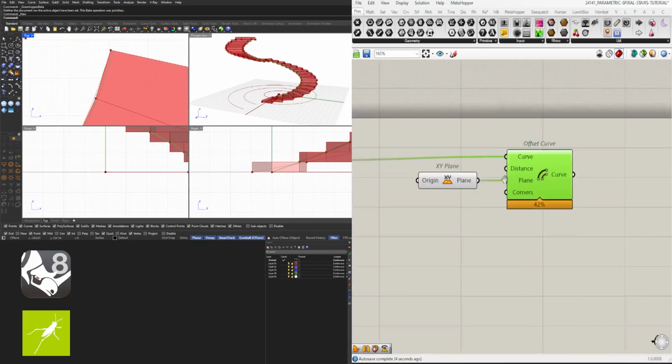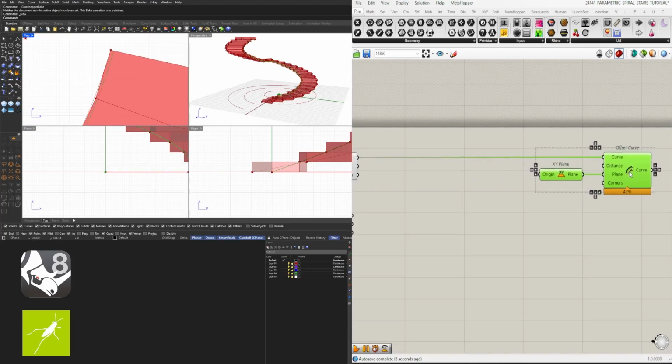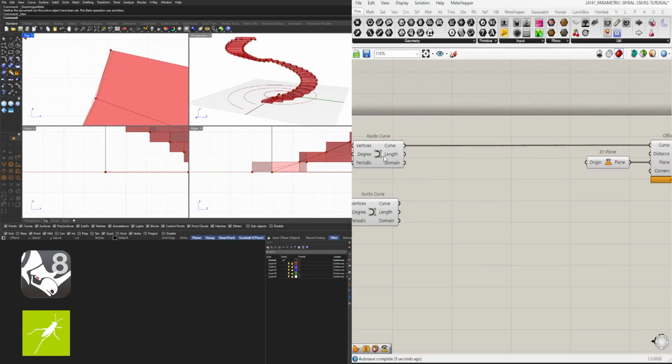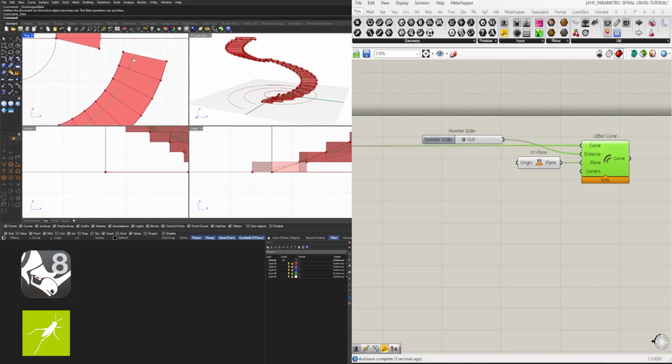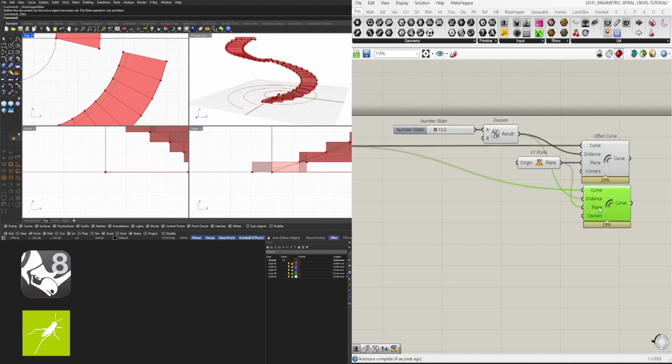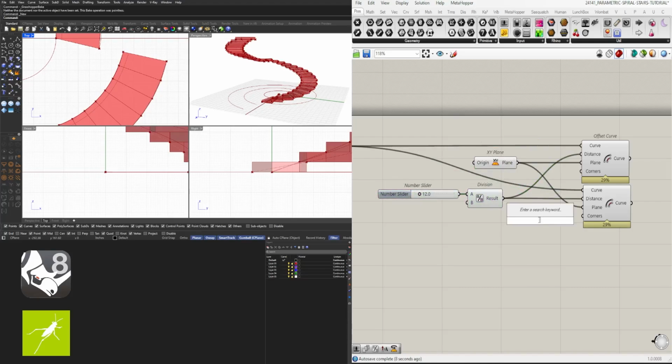We're going to offset it both to the inside and to the outside, which means that since we're using this as the center line, let's go here to 12. Since we're doing this from the center line, then 12, we actually need to divide by 2 so that we do 6 to one side, 6 to the other side. So this will be negative.